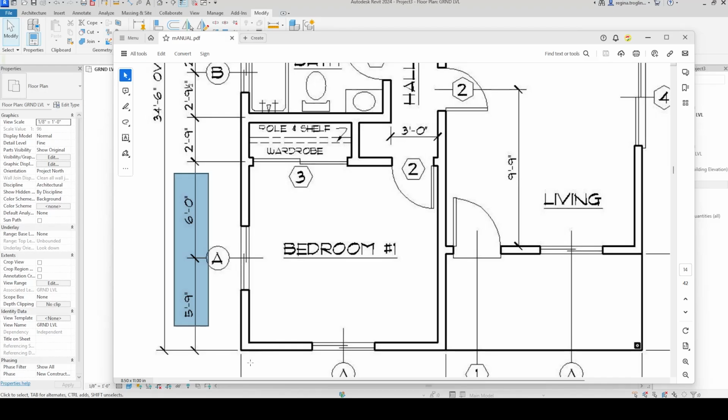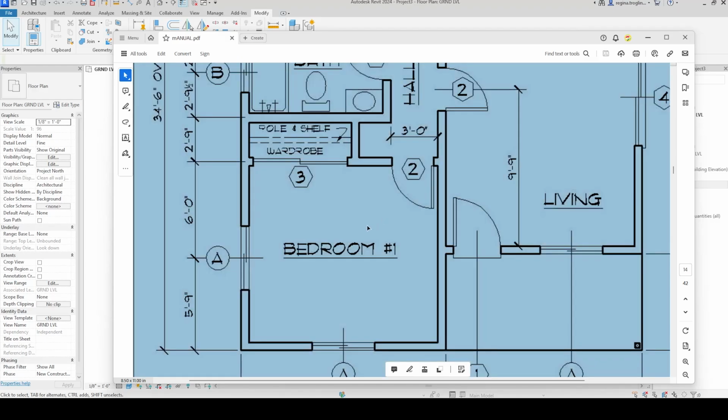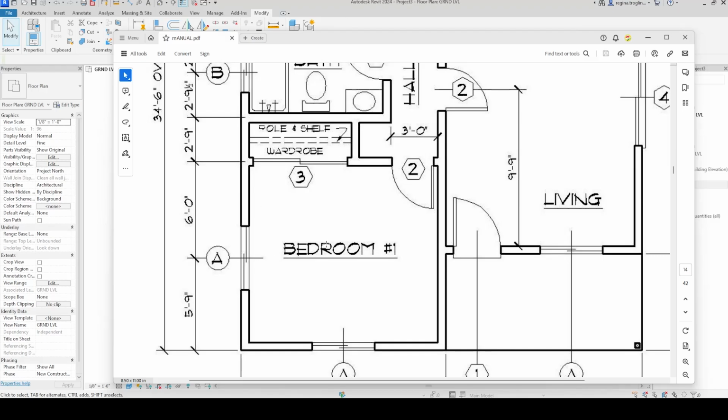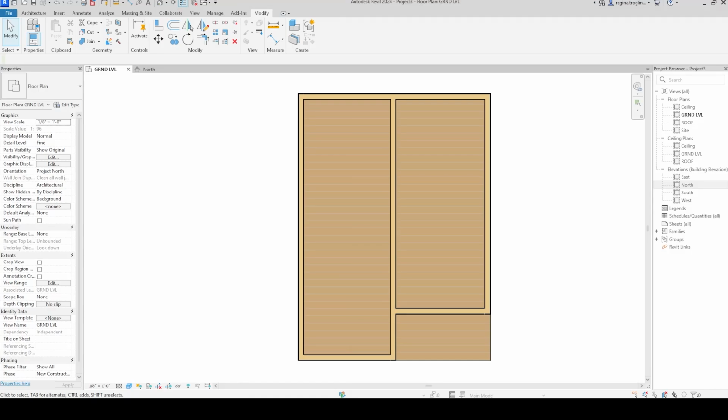The only time mostly within the architectural field, when you're dimensioning, you go from the outside edge, if it's an exterior wall, to the midline of your next wall for dimensions, especially for construction sets. So you keep that in mind. So let's go ahead and put that together. We got 6 feet and 5 feet 9, so that should be 11 feet 9.